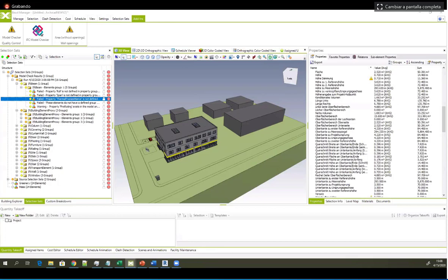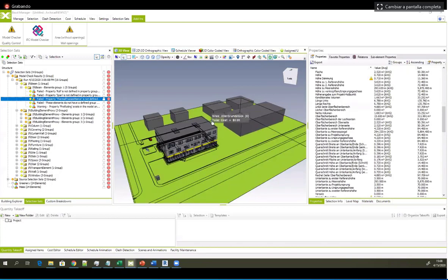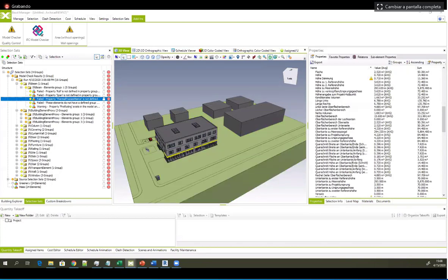What are the differences between categories and the rooms? Well, categories are different types of BIM model elements, and the rooms are just a specific type within that. So the rooms are a specific type of the spaces, IFC space. This is the way how Revit actually handles different types. So Revit has the spaces and the rooms, but within the IFC, these are IFC spaces, and you can additionally segregate these in different categories.